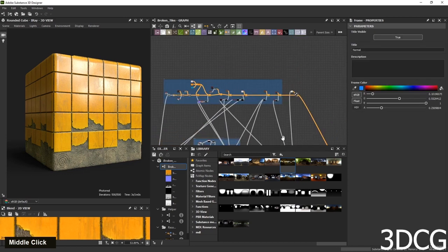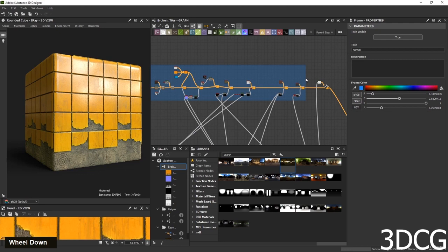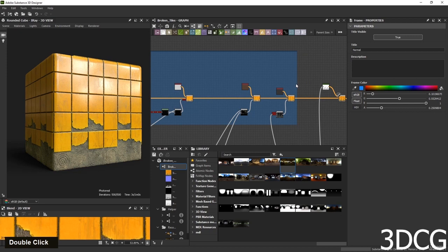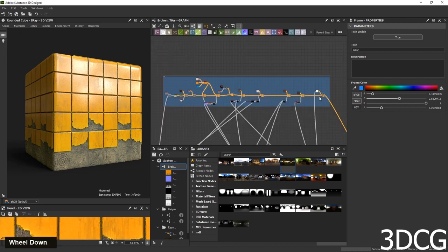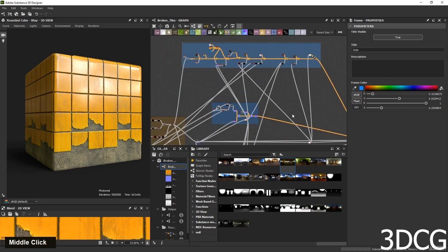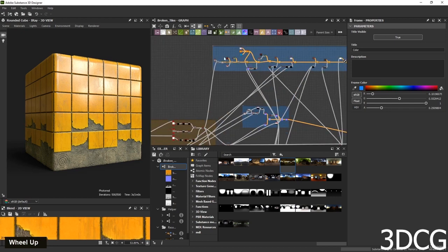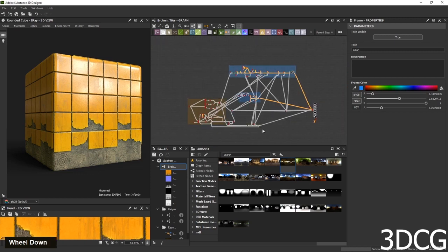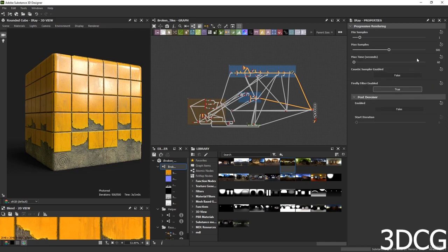You can add endless color variation or normal variation. I wanted to make a quick setup and show you how to do it. So inside the render, edit, just set up the min sample, max sample, maybe 1000, and max time.